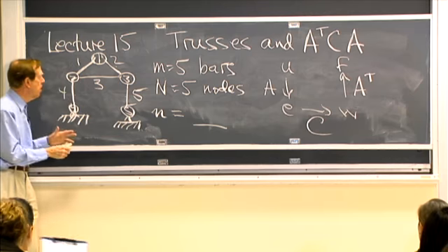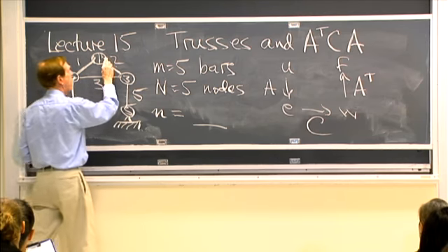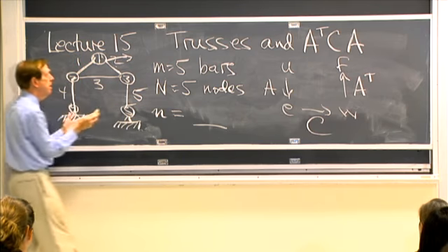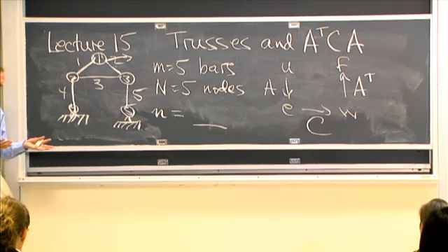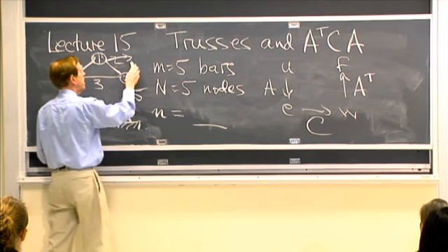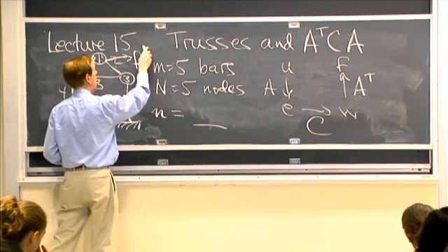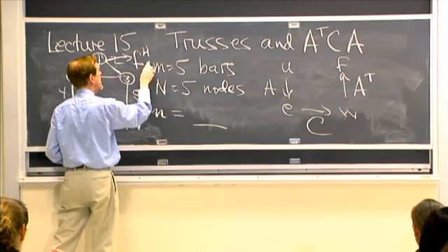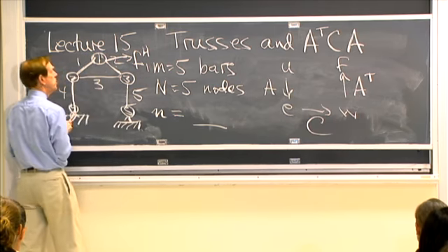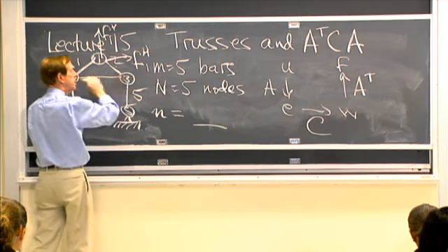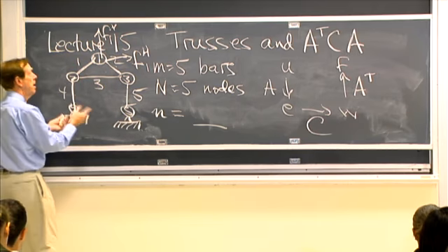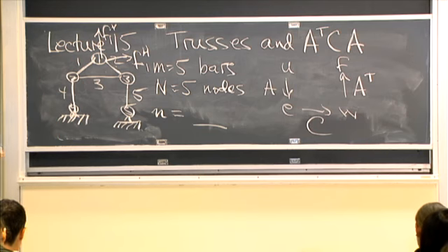We have forces in these bars, so that node 1 could have a force. We're in the plane, so we have a horizontal force and a vertical force. Together, that produces a force in any direction. So this is the key point: there's a horizontal force, F horizontal 1, the 1 being the force on node 1, but there's also a vertical force. And let me take horizontal to the right, positive to the right, vertical, positive upwards, just to have a convention.